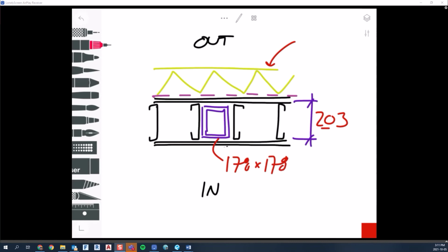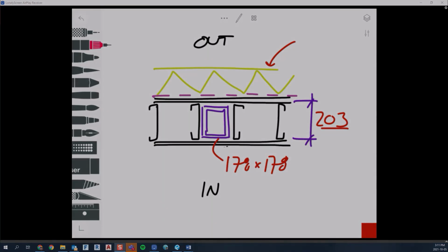So going to a 203 stud or 8" stud just created really nice construction tolerance, basically. So that's an option, but the 203 stud isn't nearly as common as the 152 stud. And of course, you're losing floor space as well, a couple or 50 mils of extra floor space.